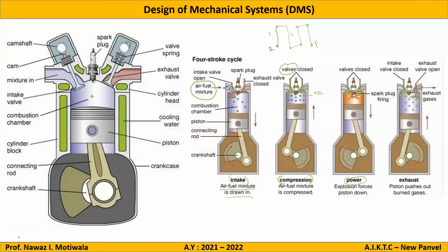Correct. Okay, so if I explain it in other terms, let us assume that this crank which I have shown in this tilted position is actually here. If this crank is exactly at the 0 angle, if I consider this as my reference, the perfect vertical one, where will be the position of the piston, below or top? Below. Just see the first diagram. It will be exactly below, that means at the bottom dead center.